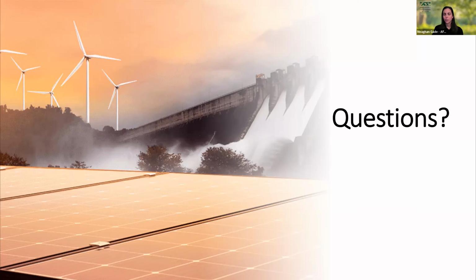So I was trying to draw the contrast between a blanket curtailment where we shut it down no matter what, if the wind speed is below a certain speed, versus smart. With a blanket, we shut it down no matter what, whether or not a species is present. But with smart curtailment, we're only shutting it down if a species is present. So that's the idea behind it. Again, there's still a lot of development that needs to happen with that technology. But yes, short answer.